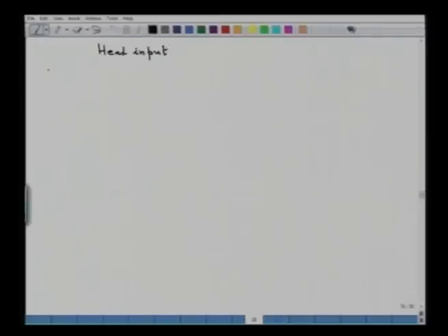So, now we are in a position to make the heat balance and analyze the heat balance. So, if we do that, we will consider, say, energy input, or we can call heat input, whichever way you want to understand. So, heat input was calorific value of coal, and that is equal to 8184 into 10 to the power 3. These values are in kilocalories.